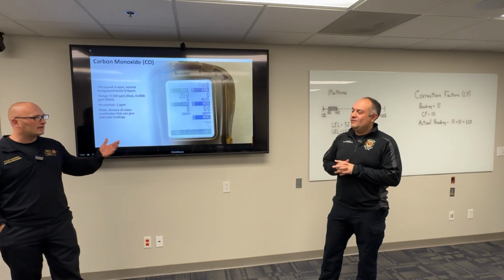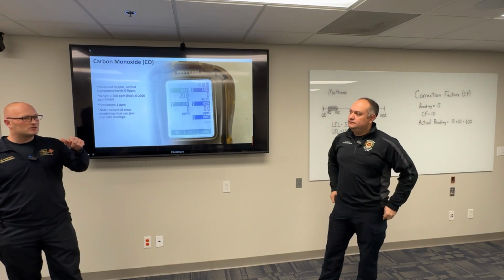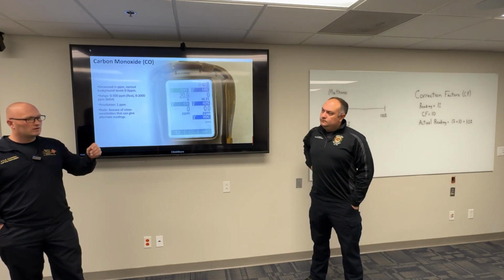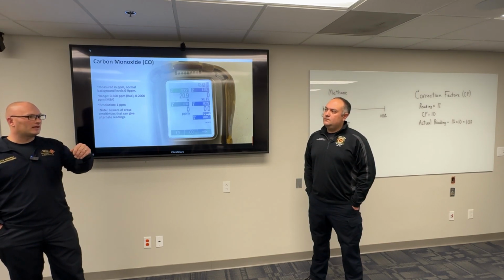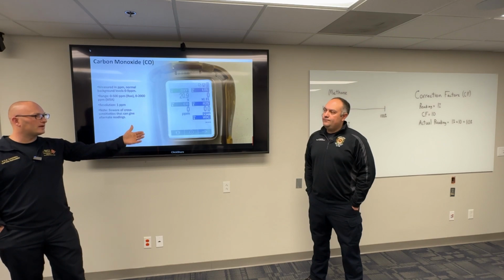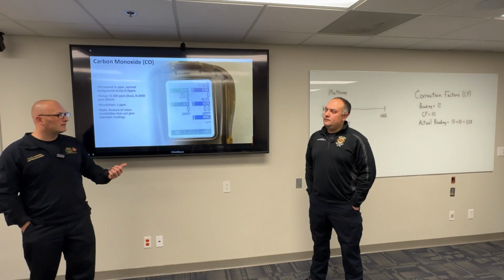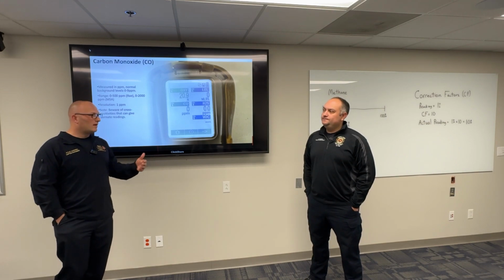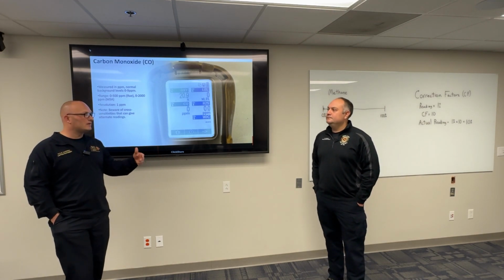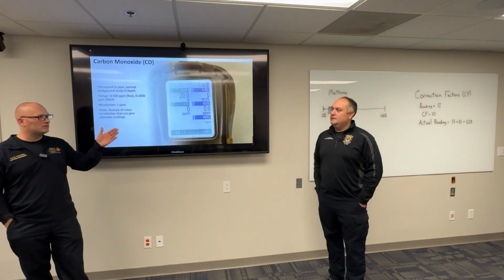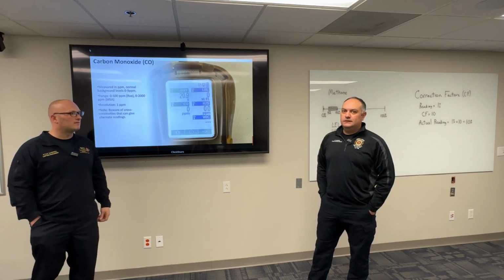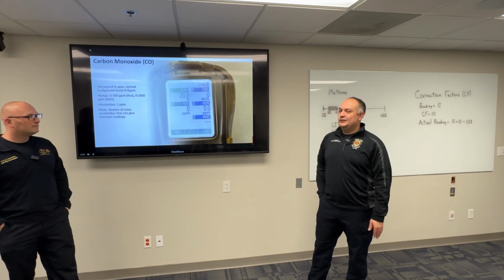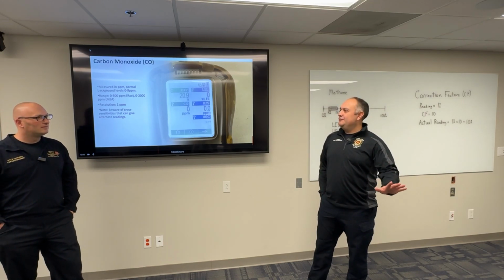So another thing we have seen in the county, multiple places, apartment complexes and townhomes. I know there's been 2 or 3 actual fatality CO calls where they went into a townhome with the CO alarm going off, thought they had everything checked, and then said, you know what, let's check the rest of the buildings, and the apartment next door was the one that actually had the leak and had stuff pegged at the door, and that was where the fatality was. So never take for granted that, hey, I found this, especially in big buildings, apartment complexes, and townhomes. Actually do justice and search as much as you can until you can absolutely verify that everything's safe. Yeah, be vigilant, get your own readings if you can. Don't trust readings that are not from your people.